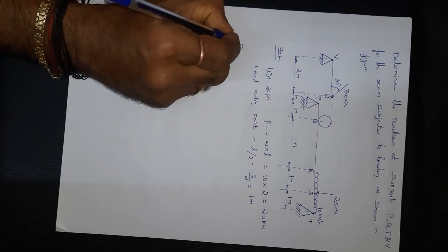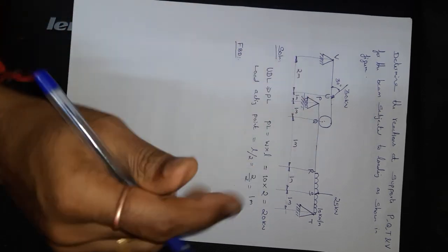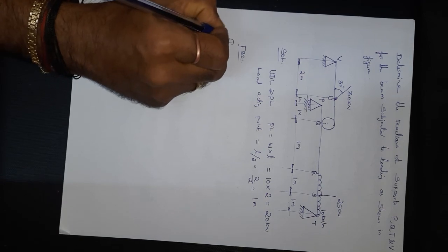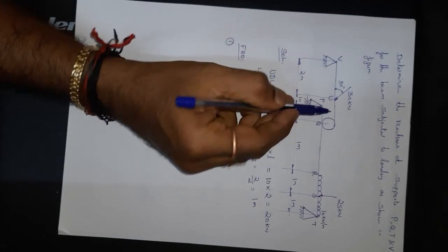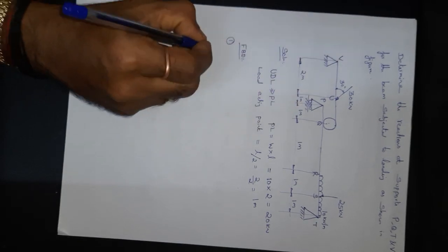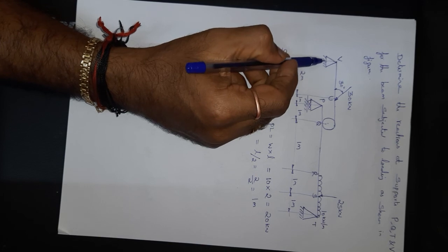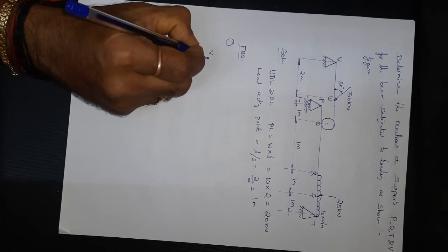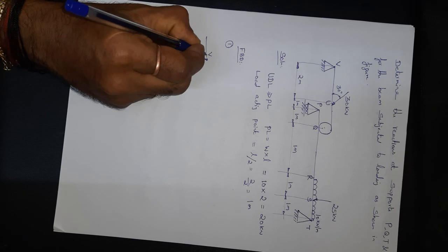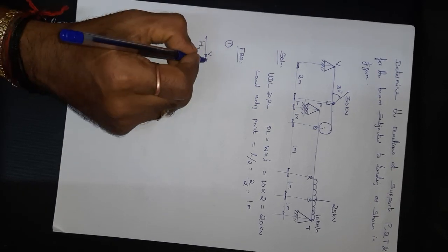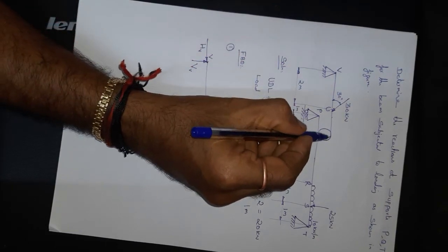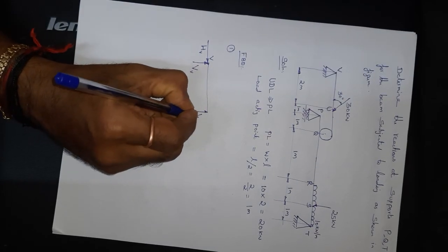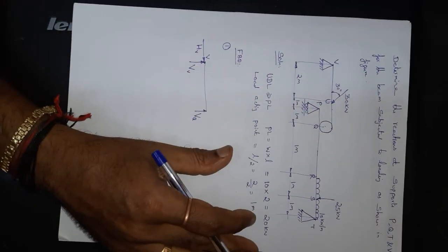Got it? Now I am going to draw the FBD. As far as this diagram is concerned, since there are two beams, I need to draw two FBDs. Let me draw the first FBD for the small beam, wherein at point V, I have a support which is a hinge support, which will have two reactions, isn't it? Vertical VV and horizontal HV. Let me extend this beam here, and look here, this is a roller support which will have one vertical reaction, which can be taken as VQ.